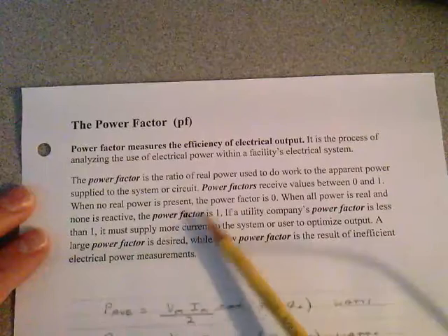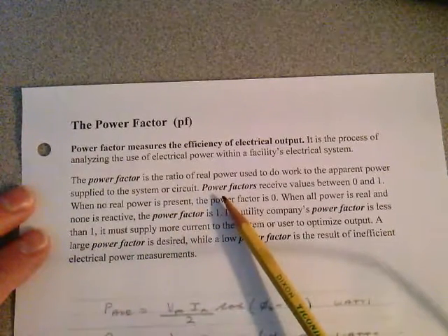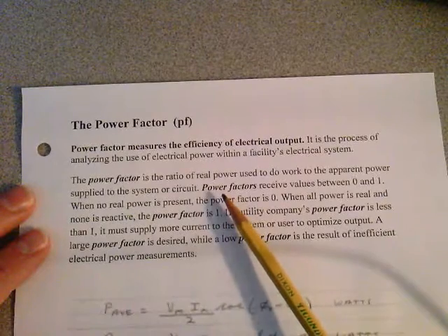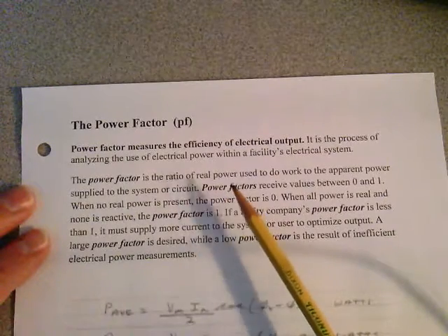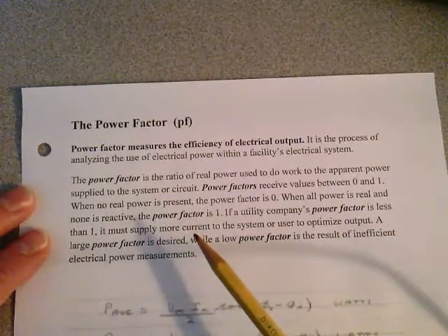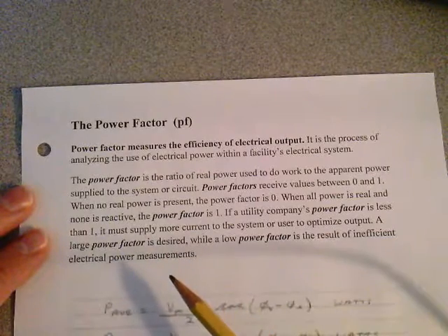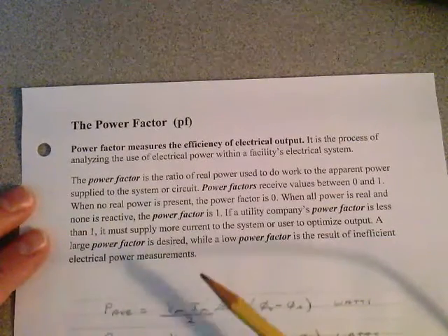I'm going to paraphrase that a little bit. Whenever you have a purely resistive load, the power factor is going to be 1. Whenever you have a purely reactive load, the power factor is going to be 0. You'll see that in a minute.